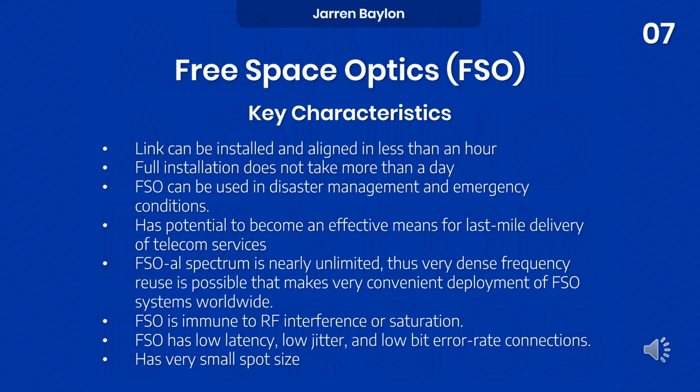The FSO optical spectrum is nearly unlimited, thus very dense frequency reuse is possible. This makes deployment of FSO systems very convenient worldwide. FSO is also immune to radio frequency interference or saturation. It also has low latency, low jitter, and low bit error rate connections.